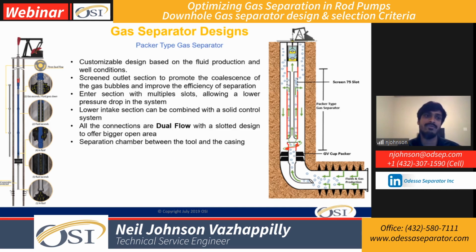Right. So the flow path, we're going to see a video again, but if you look on the right hand side, we can see the fluid from the formation has to travel inside of whatever we have right below the packer, and the fluid has to go inside of the separator. That's what the packer is supposed to do, redirect the flow inside of the separator around the dip tube, traveling upwards, and then the gas liberation process, which I'm going to show you in the next slide, all happens inside of this gas separator.